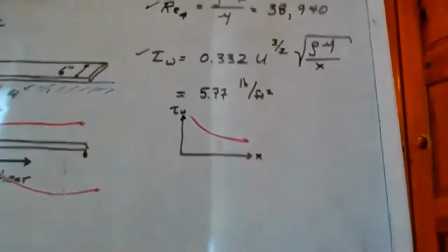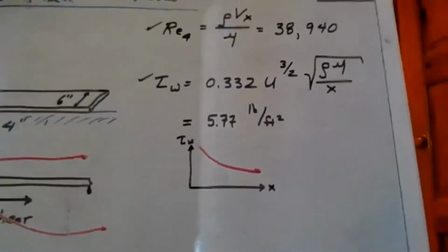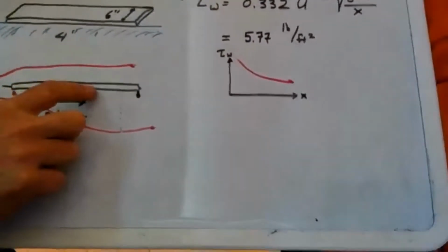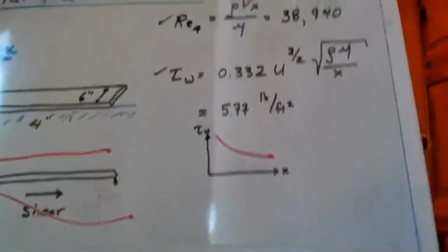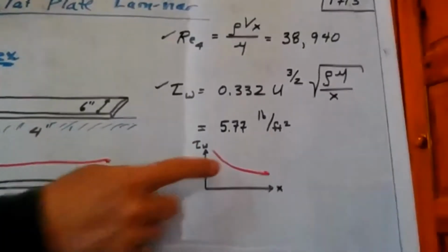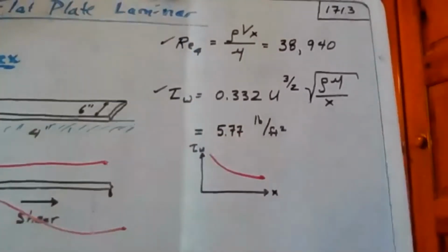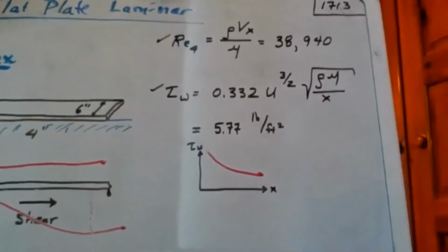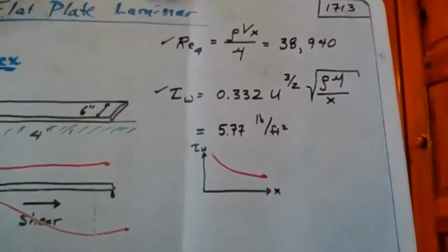Okay, well, what you need to do then, essentially, if you want to get the drag, is you would have to go point by point along here and get the shear and multiply it by the corresponding area. Essentially, you would need to do an area under the curve and an integration. And that is possible to do for this formula, and that has been done. And so a formula that puts it all together has been arrived at, and that's what we'll take a look at next.